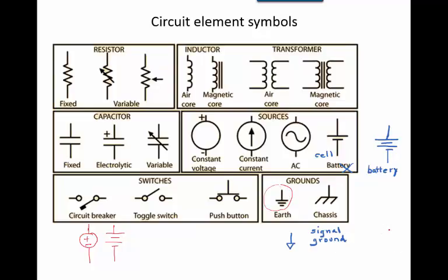Chassis ground. Chassis ground is this metal case surrounding this oscilloscope. So inside, there's circuits inside this instrument. The circuit cards inside this instrument have some physical wire tied to this outside metallic housing, or sometimes it's an inside frame. That's called a chassis ground. So an assembly drawing might have a symbol that says tie the circuit right now to a chassis ground. Chassis ground and earth ground are very often tied together. All our instruments have a chassis ground and earth ground tied together.